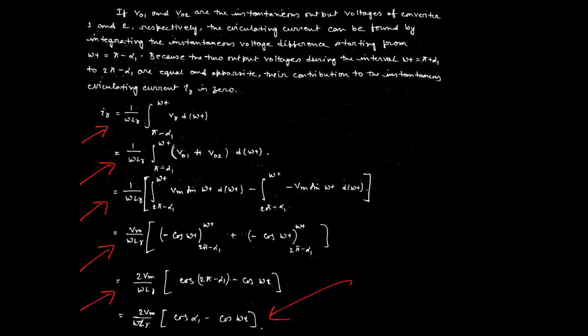If alpha 1 varies, suppose, from 180 degrees into the next cycle, then the second converter can provide the negative current. So in this way we can adjust alpha 1, by which we can control the converter output across the load, that is across the motor. Then we can easily control the direction of the motor as well as the speed of the motor. So this is all about the single phase dual converter with a good example of a DC motor.